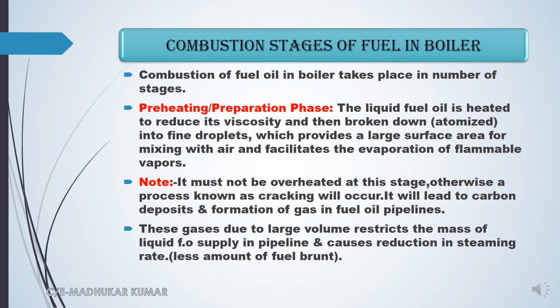And then again, these gases mean the flammable vapors, and these vapors are having very large volume, and then this restricts the mass of the liquid fuel oil supply in the pipeline, because when we talk about the fuel oil pipeline, the volumetric capacity is basically fixed as per the cross sectional area.